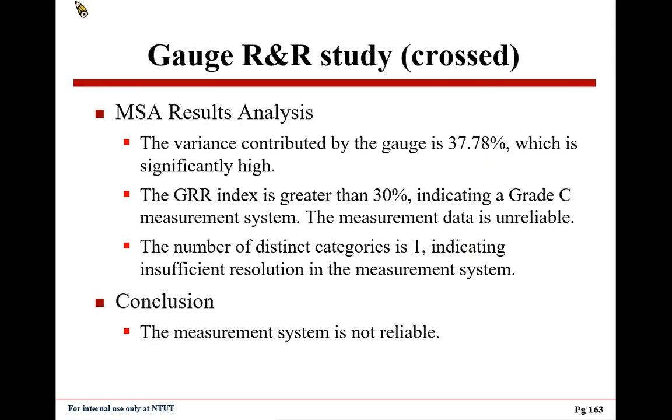So we will make a quick conclusion of this analysis. Firstly, the contribution of the measurement system is about 37%, which is larger than 30%, so it is unacceptable.